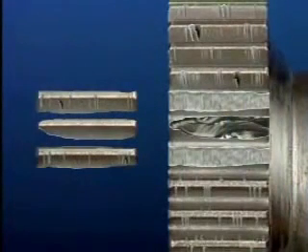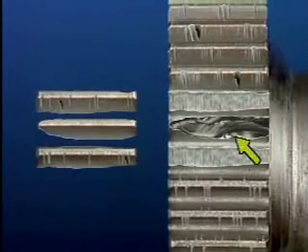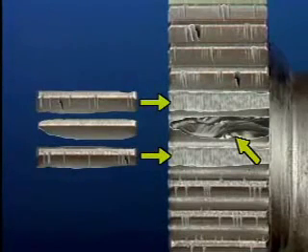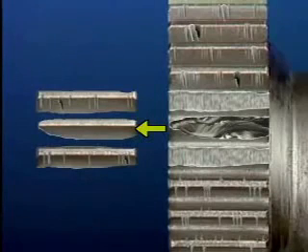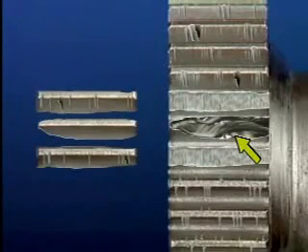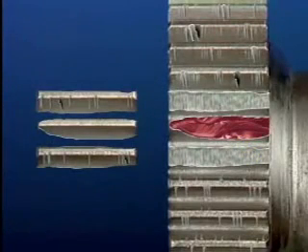A close inspection of the broken gear in this case shows fatigue failure with a well-defined eye and adjoining teeth broken by overload with a rough appearance. A look at the crown or top portion of the tooth that broke due to fatigue failure indicates that the tooth was not deformed before it failed. This is also evidence that an external overload was probably not a factor. Now, if the fatigue break area contains a large amount of reddish stain, as it does in this example, then that indicates that the break took a long time to develop and is further evidence of an internal defect.